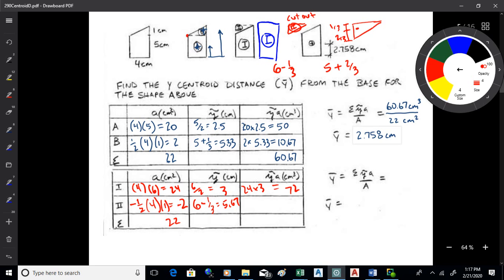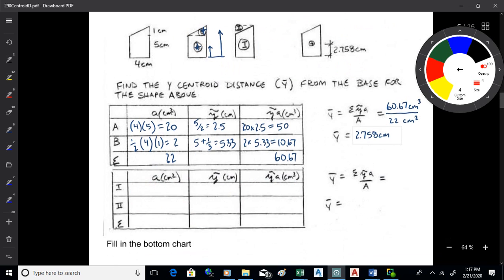So just pay a little bit of attention on those triangles. Rectangles are symmetrical; whichever side you start on, you're going to get the same thing. But the triangles, you've got to watch. If you're coming from the right angle side, it's a third. But if you're coming from the vertex side, the acute vertex, it's 2/3. So just remember that. And then remember the negatives also.